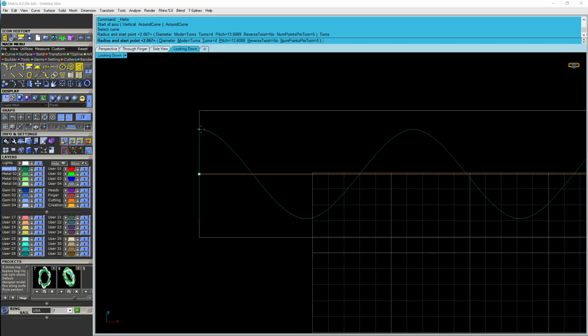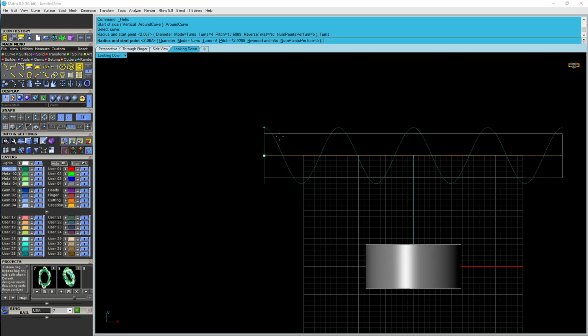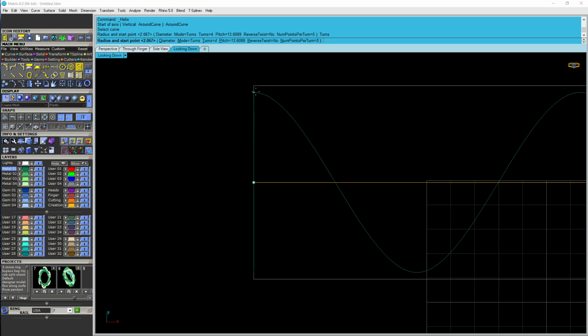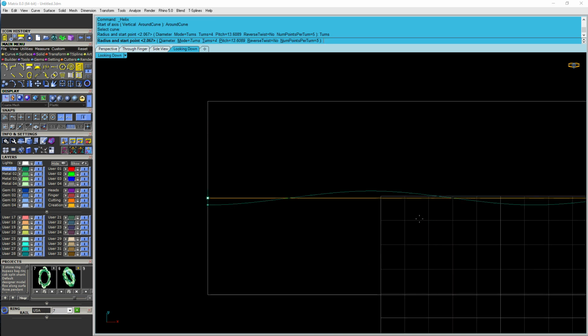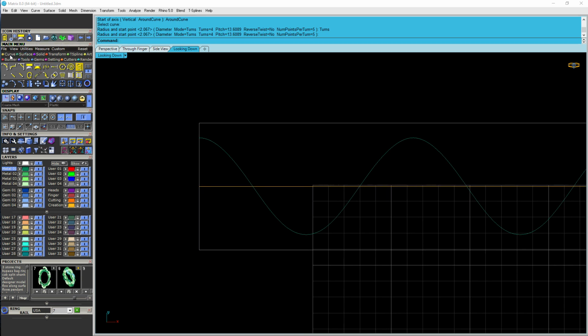So whatever thickness or width each strand is gonna have, you need to stay away that much. So say we have a 1.75 thick, divide 1.75 in half, put your curve, and snap to that endpoint. Or speaking of endpoint, you can just say 1.6. We'll draw that there.